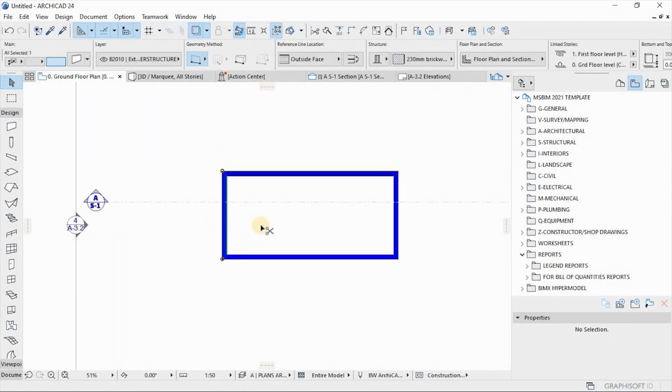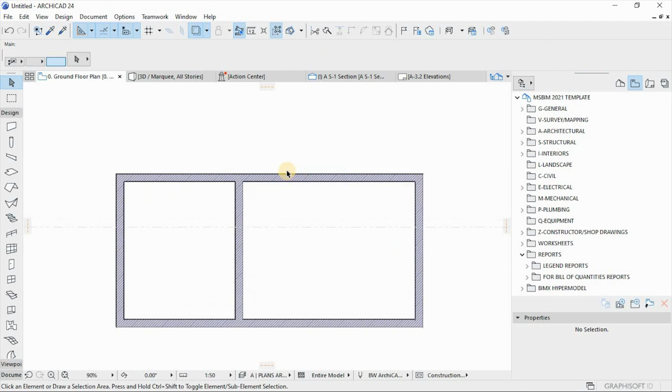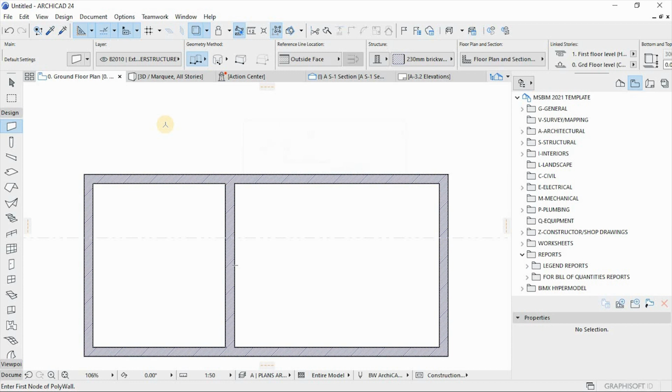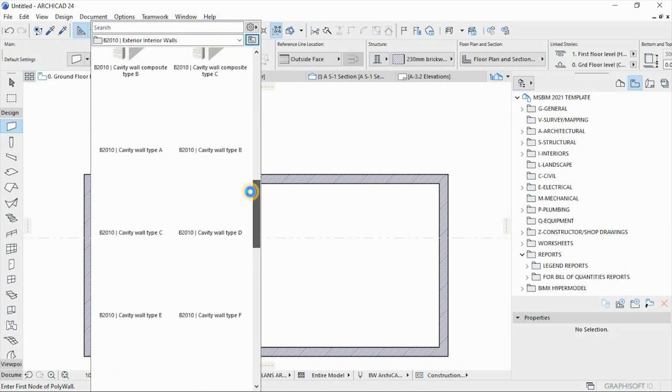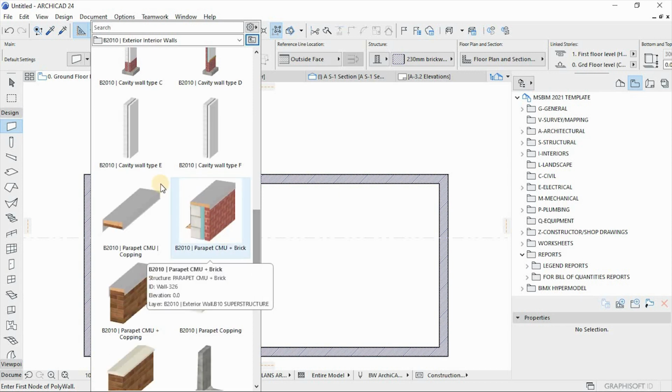So from here, I'll suspend groups, duplicate this by Ctrl+Shift+D, and then create a 3.5 by 4.3 space for the bedroom. This will be for the bedroom. And then pick the parameters of this, go back to the favorites of brickwork, and find something that you can use for the partitions.